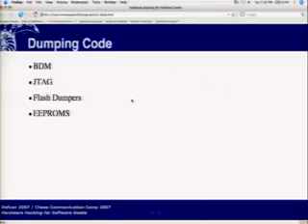It supports a lot of the same stuff as BDM. Basic JTAG won't let you do debug. It won't let you step the clock one step at a time. It won't let you access the registers. It will, however, let you set or clear the state of any pin around the device. Basically, the JTAG talks to a chain of shift registers that sit between the actual metal pin on the outside of the circuit and the silicon inside the device, and allow you to change these pin states without the chip itself actually running. Okay, we got to run.